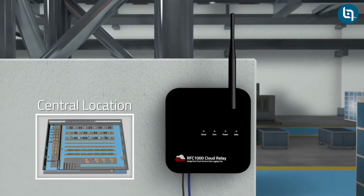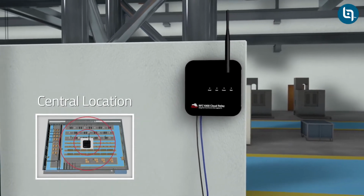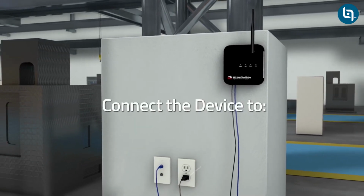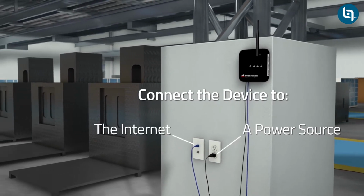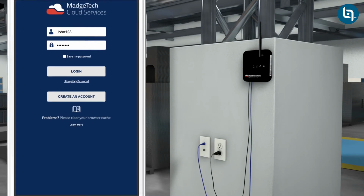First, determine a central position for the RFC 1000 cloud relay. Be sure to mount or place the device in an area with access to both power and direct internet access. Plug the cloud relay into a power source, then connect the device to the internet with an Ethernet cable. Once connected, navigate to cloud.madgetech.com and sign in.